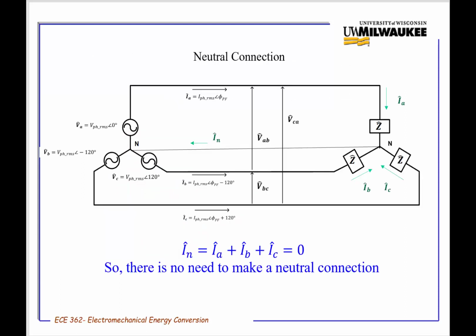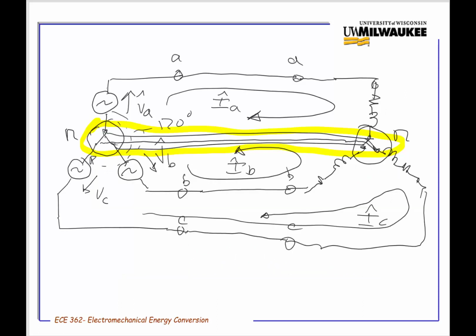What I'm looking at here is a three-phase source connected to a Y load, and there are three lines, A, B, and C, that are connected together. In the sketch that I drew, I indicated that these three return lines are all connected together, and that there could be a fourth connection here, a fourth wire connecting the two sides, a neutral wire.